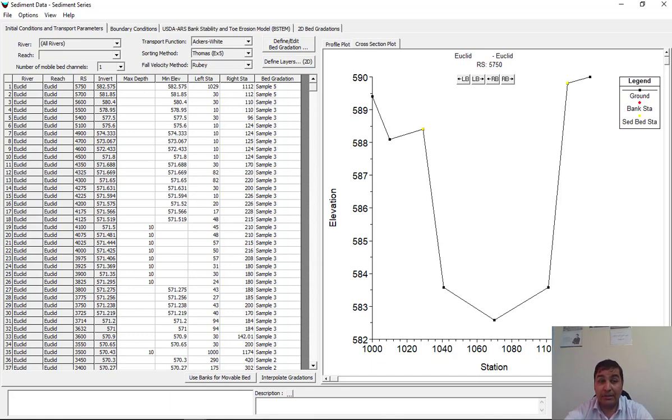Armor layers decrease total transport because the surface particles available for transport tend to be coarser and more difficult to move. If you use only sediment transport functions, it does not lead to realistic results because, as I mentioned, transport functions compute only transport potential without accounting for sediment availability, and they don't consider armoring effects on sediment transport.